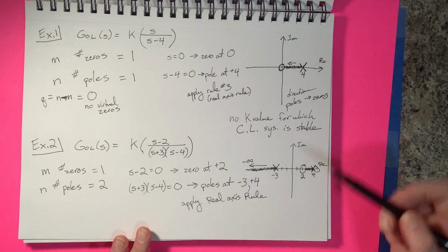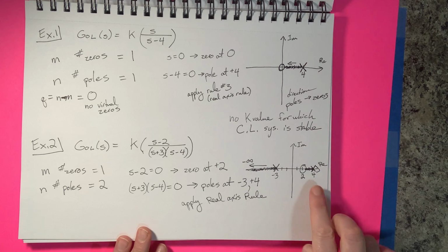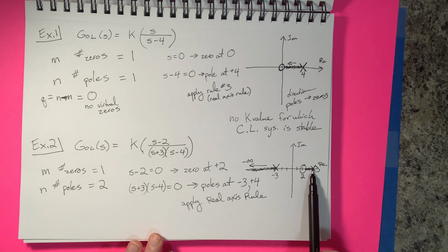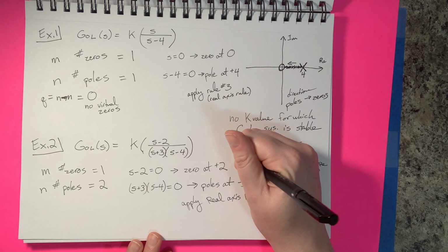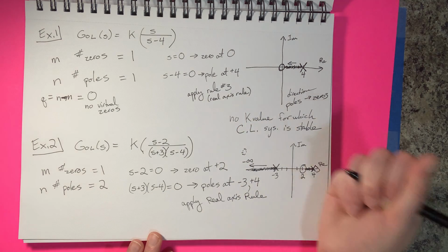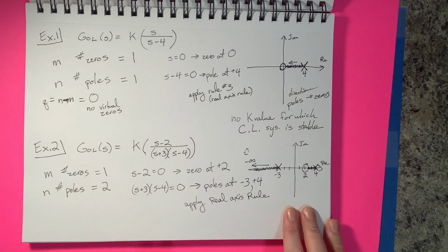So in this case, we have completed our locus, and we will see that we have the root here, the pole here, it migrates towards this 0, and then this pole will migrate towards a virtual 0. And then that would complete our locus plot.